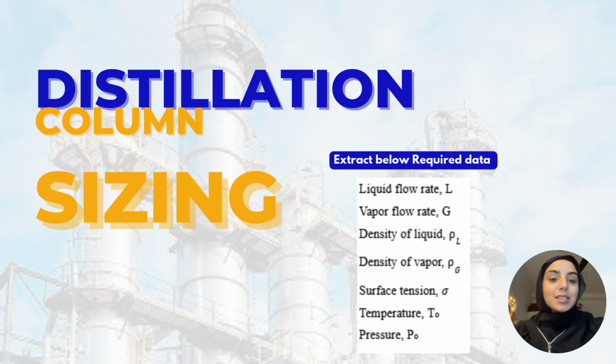Now moving into sizing a distillation column. Before starting calculation steps, you're encouraged to gather these essential data such as liquid and vapor flow rates, densities of both liquid and vapor phases, operating temperature and pressures.